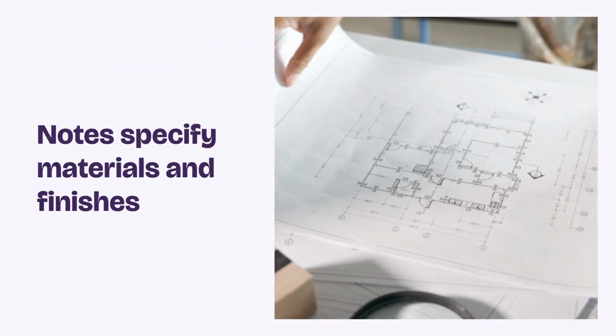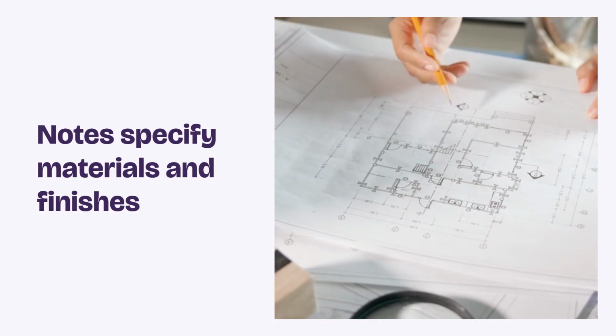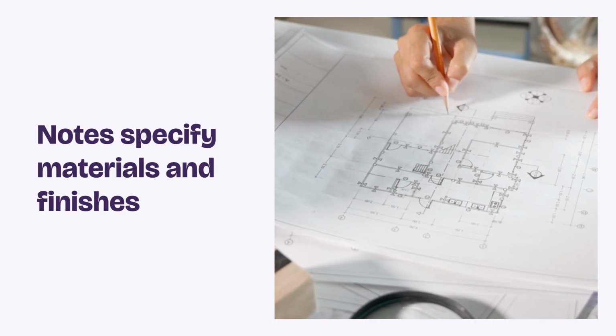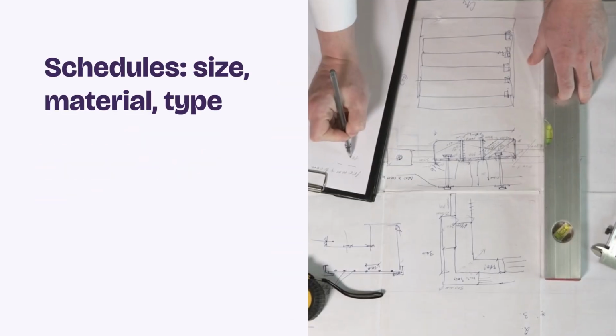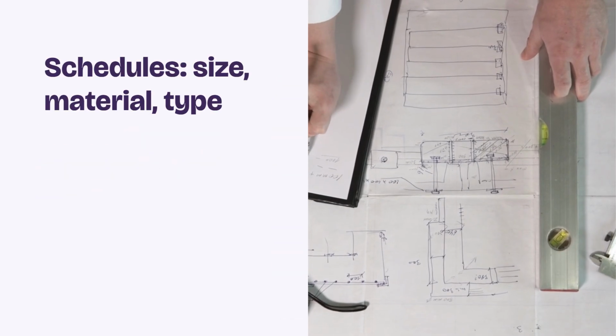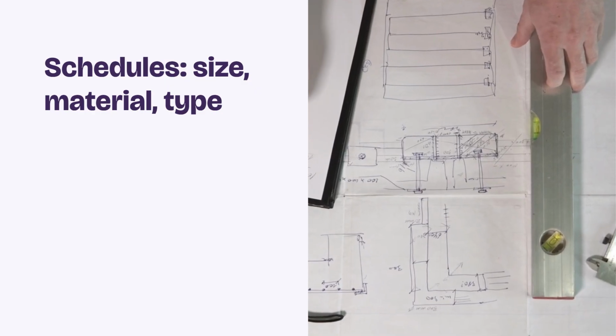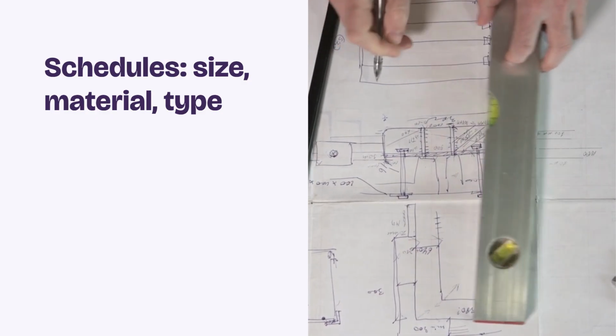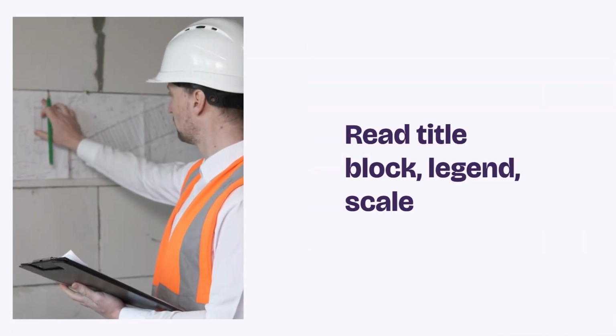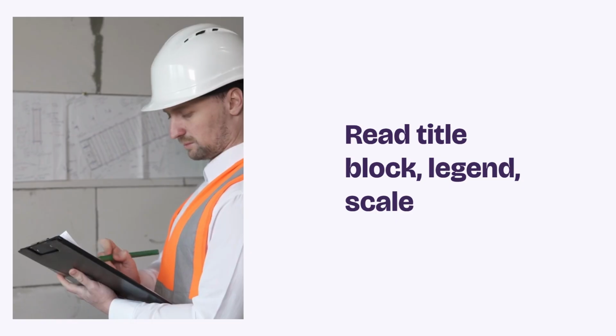Don't overlook the notes and schedules. These are side sections on the plan that specify materials, finishes, or installation instructions. Door and window schedules list every opening in detail, the size, material, and type, making ordering and installation clear. Every symbol and line has a purpose, so take your time.